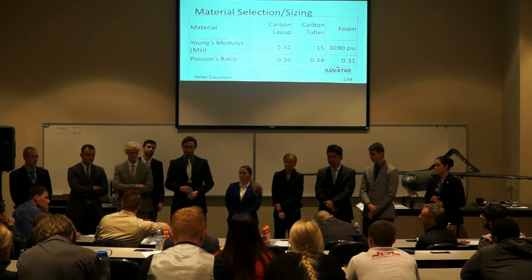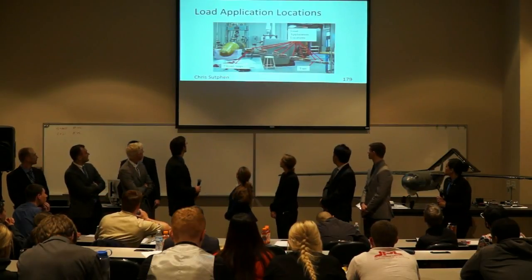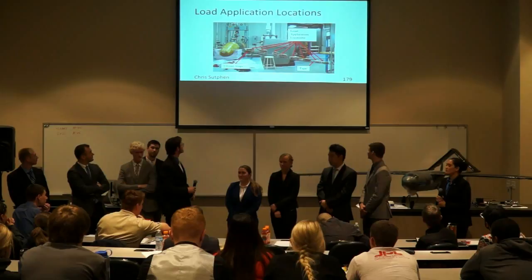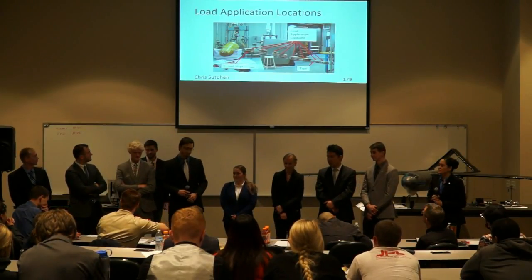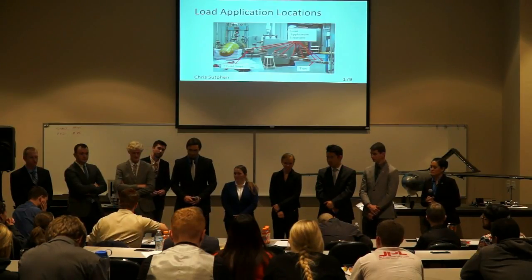Yeah, we observed the same thing. If you go to slide 179, it's a picture of your test, and you can see where that joint is, and where it totally bends. We saw the exact same thing, so I'm glad you guys caught that. That's what we figured too, that amount of space you could wiggle in that joint leads to that big deflection.